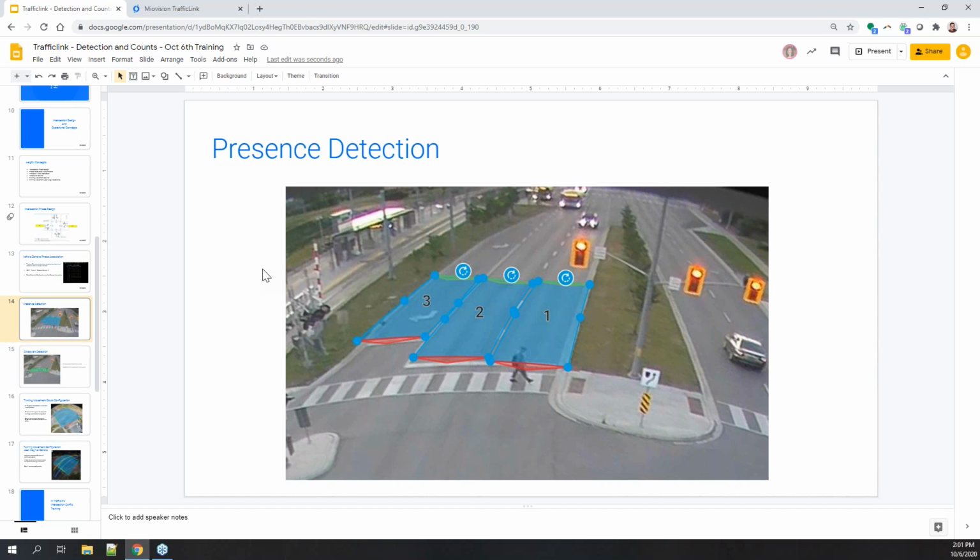It's a good question. I actually get asked that question quite a bit. To us, it doesn't necessarily matter. Often when I do lane-based, it's because we have a lot of detector channel options. We can use all the channels, so why not use all of the channels? But for simplicity, you could just do one zone for an entire approach, and then you really only have to worry about one channel to one phase instead of like 3 to 4 channels to one phase. So it's just the appetite for complexity or specific intersection operations. But to us, there's no difference in benefit necessarily.